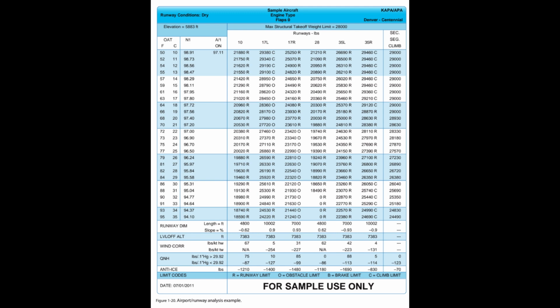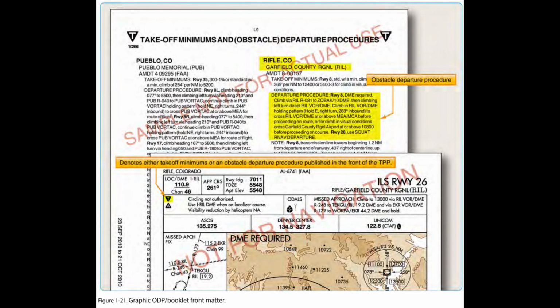Obstacle Departure Procedures, ODPs. The term ODP is used to define procedures that simply provide obstacle clearance. ODPs are only used for obstruction clearance and do not include ATC-related climb requirements. In fact, the primary emphasis of ODP design is to use the least restrictive route of flight to the en route structure, or to facilitate a climb to an altitude that allows random, diverse IFR flight, while attempting to accommodate typical departure routes. An ODP must be developed when obstructions penetrate the 40:1 departure OCS, as described in FAA Order 8260.3. Only one ODP will be established for a particular runway.